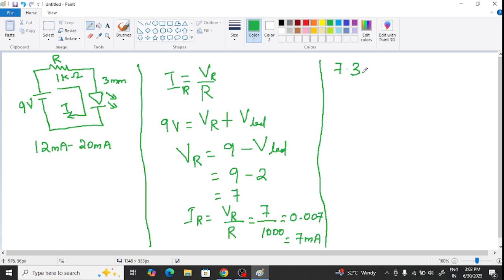This is because the moment you connect some loads or components to your source, there will be a voltage drop in the battery also, because of the components available inside the battery. So we have to check what is the voltage in the battery after connecting the circuit to your battery. Before connecting our battery to the circuit, it was 7.3, and after connecting the battery to the circuit, you can see it is only 3.9. So this is because of the drop.